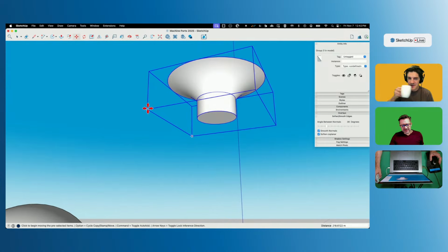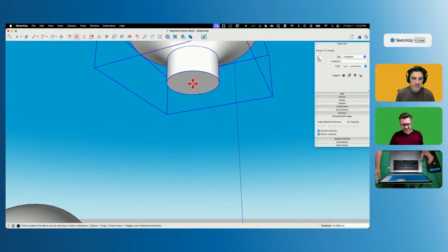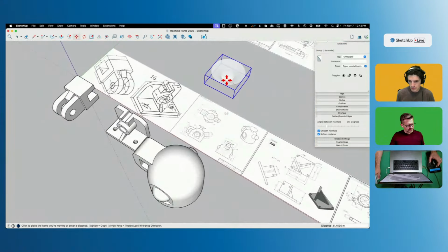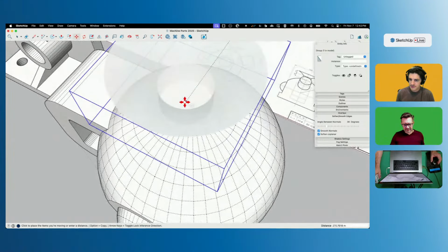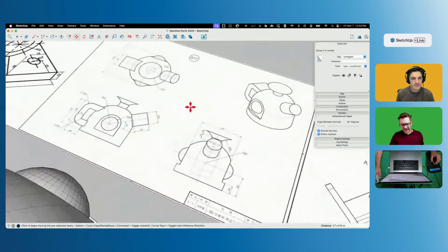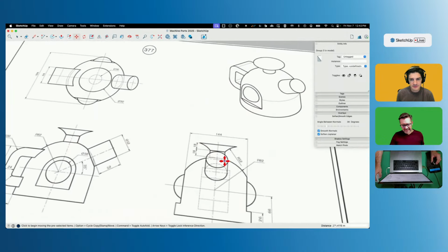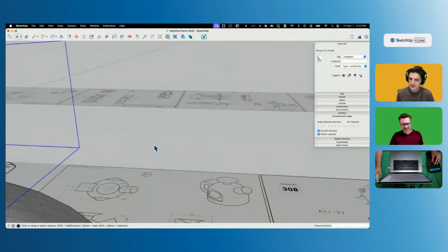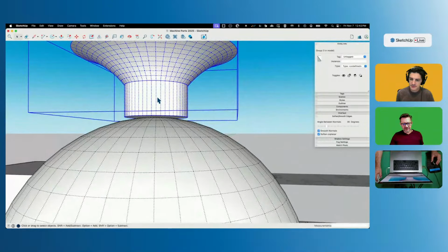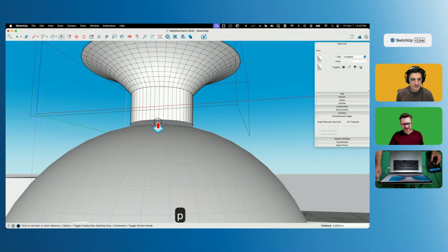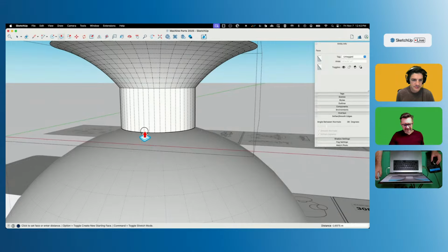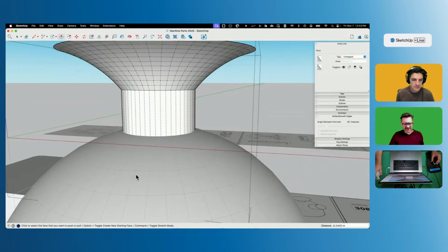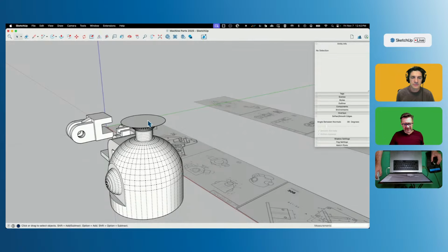So when I go to move, see my corner dots right there? I can toggle those. Oh, never mind. I got an easy snap point at the bottom. It kept my circle. Click right there. And then again, flip on show hidden. And click right there. That vertical dimension of 18 was from the point that it hit in the center. So it's right now. So all I have to do is come in here, push pull this down so it hits my face or goes past. So if I go past, then I can just use solid tools again to clean it up.